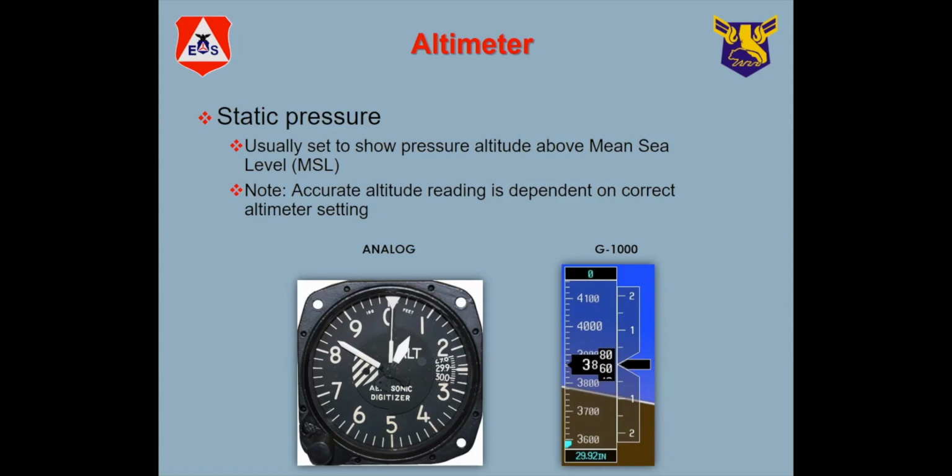And I guess the only other thing I'd say is remember that the pressure altimeter, which is the one we're talking about here, gives you your altitude above mean sea level, not above the ground. It tells you how high you are above the sea. So if you're flying over terrain that's 300 feet, let's say, then your actual elevation above the terrain is 540 feet in this example. So basically, it's important to know this so that you don't run into stuff. That's the easiest way. On the right-hand side, you'll see a display of altitude in a digital format.